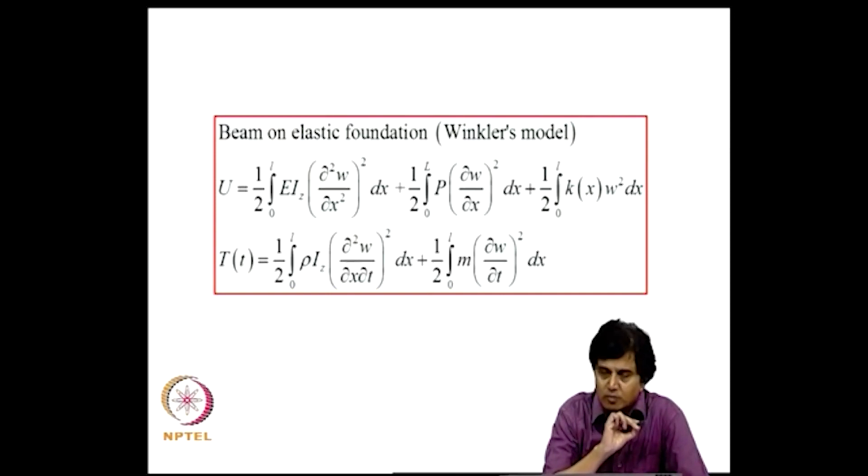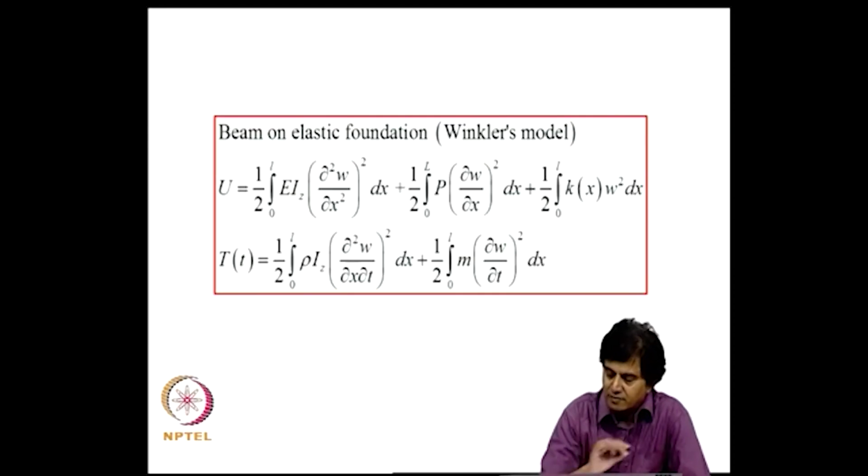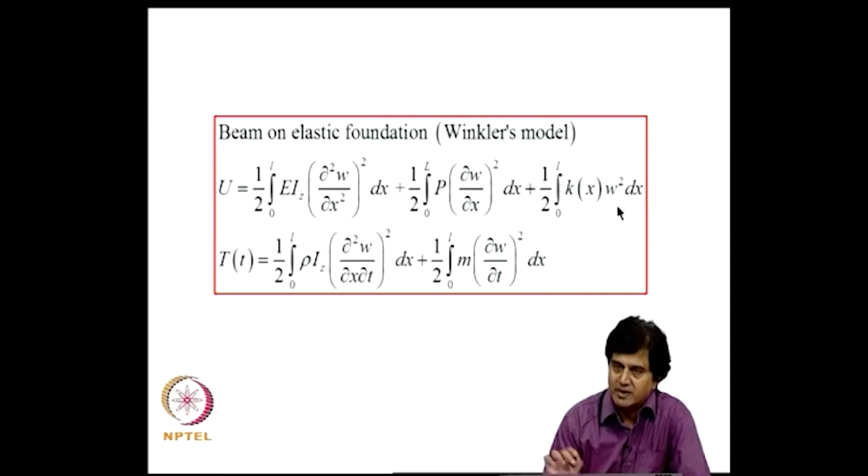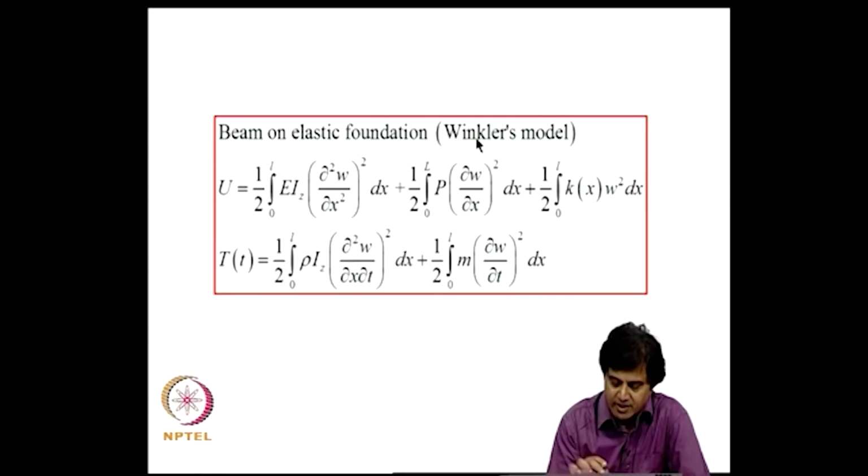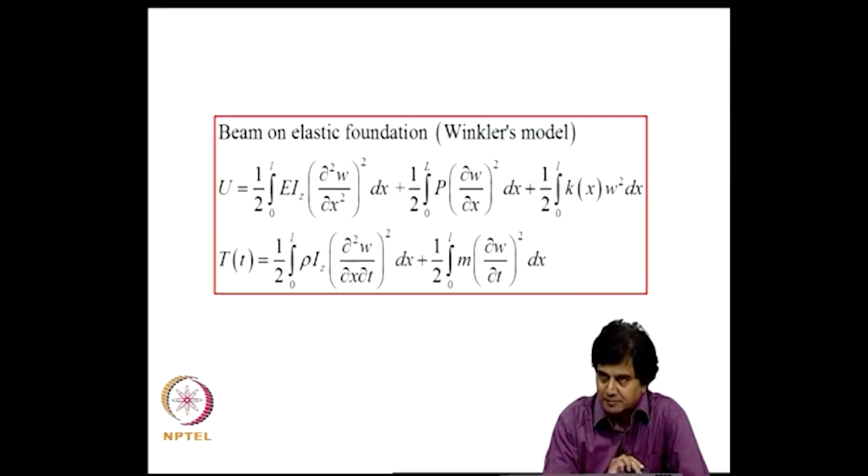We also have problems where beams rest on an elastic foundation. One of the typical models that we have for beams on elastic foundation is the so-called Winkler's foundation model, where the force offered along the length of the beam is proportional to the displacement. Now, if I consider a beam resting on an elastic foundation carrying axial loads, and I want to develop a Rayleigh's beam theory for that, say.